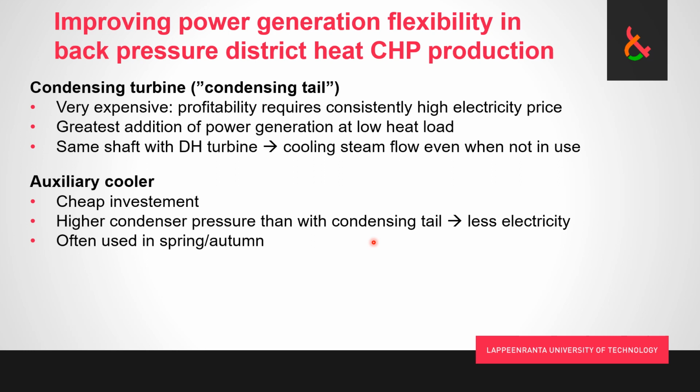And so basically, on one hand, we get to produce more electricity when the price is worth it, but we also get to extend the operating time of the CHP plant so that we don't need to fire up our heat-only boilers that produce heat with very expensive fuels quite so early, when we can create some additional load and we can extend the minimum load stoppage point a little bit further down the line.